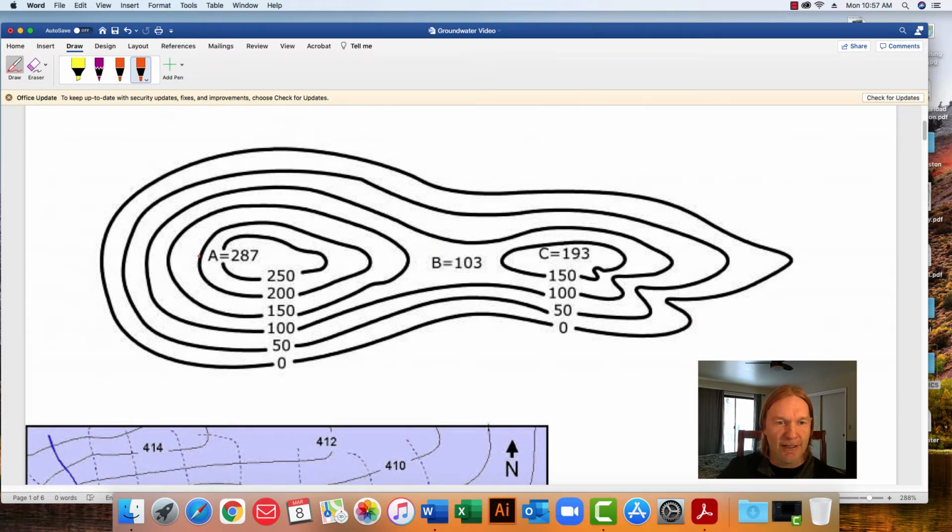Okay, so these are the same contour lines, but we're looking down on these two hills from above. Notice that here is that little drainage, so water is going to be draining off that way. And notice how the contour lines form little V's that point upslope. Okay, so the water is flowing down this way, the contour lines V in the upstream direction.